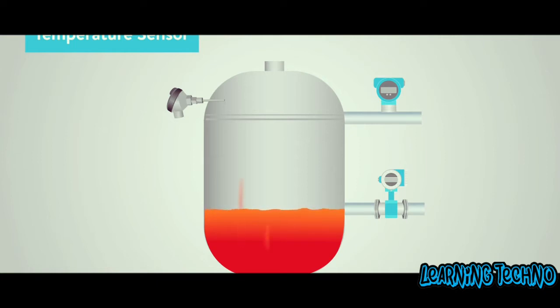And a temperature sensor is a device which will transform the temperature into an electrical signal, no matter how tiny the amount of this signal might be. So far, I took a big first step, which was the transformation of temperature into electrical signal. Based on different sensor technologies, this signal may have different ranges, and for industrial applications, I need to have my signals limited to some universally accepted electrical signal ranges.